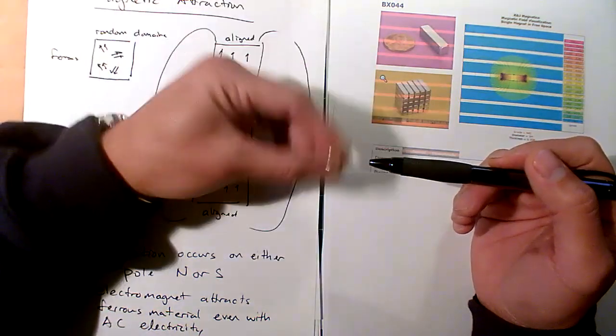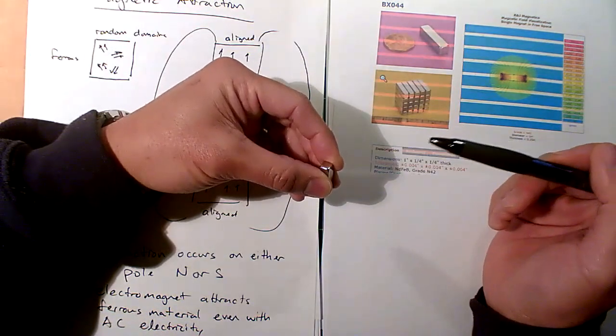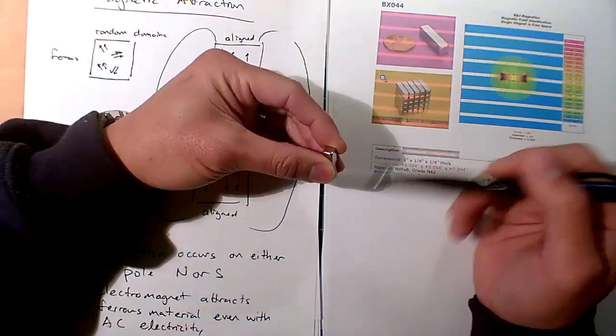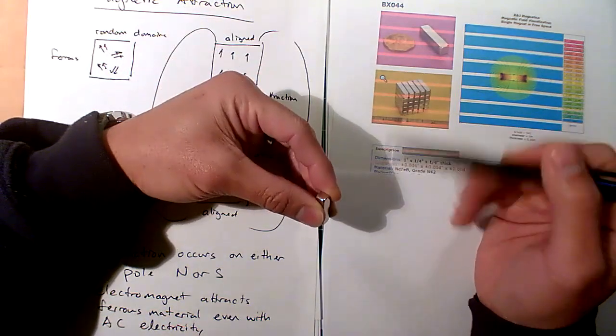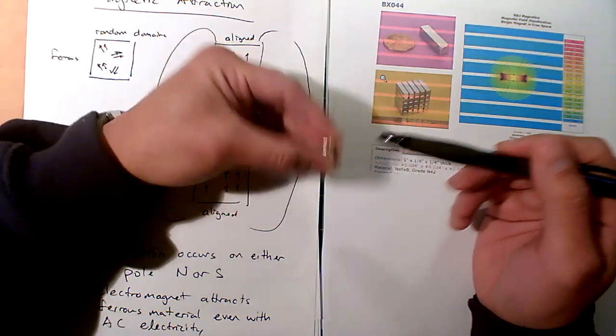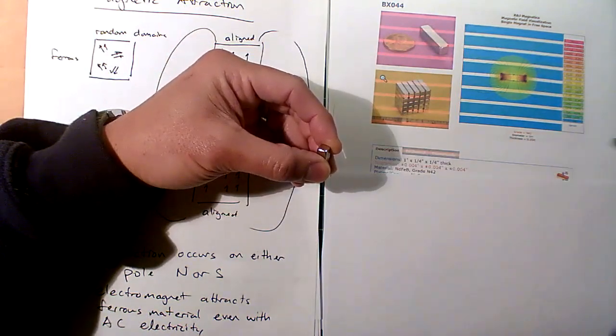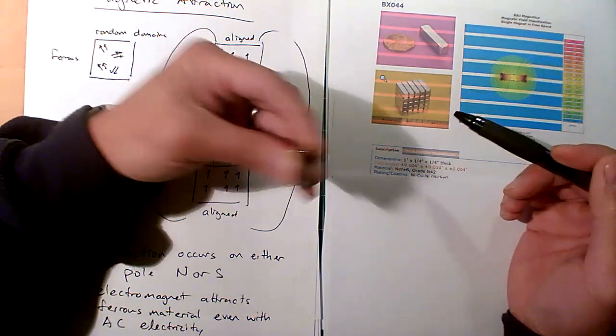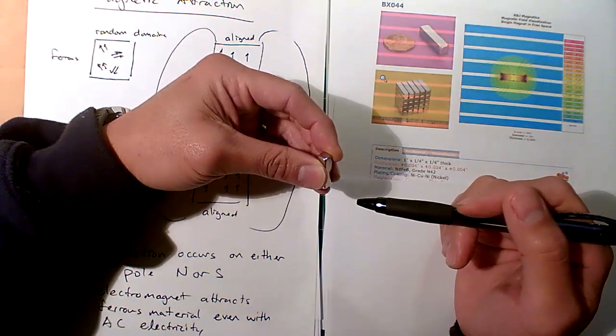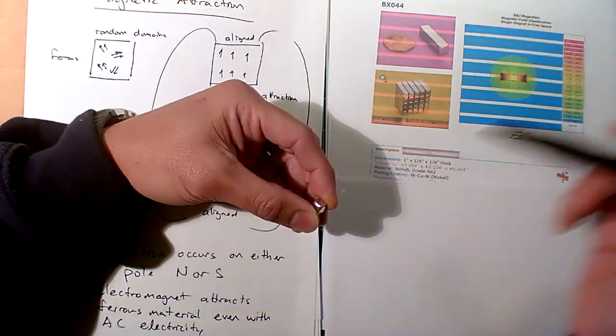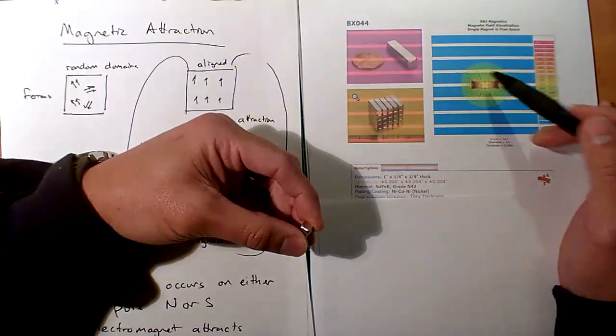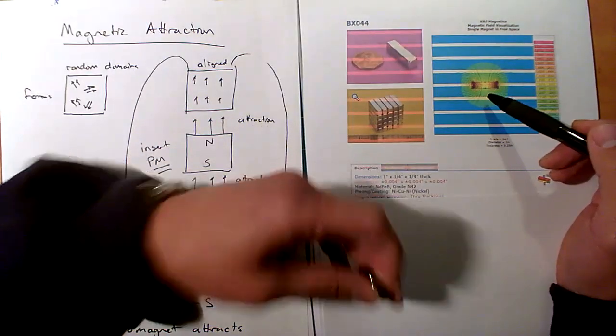If your magnets are spinning, you're not going to induce any current if it's a generator situation, and vice versa. If your current is here, it's going to be more difficult to lock on and maintain that force. So you want to get your magnets as close to your coils as possible without rubbing and all that stuff. I know it's hard to see on this. I'll print a better copy in the posted notes.